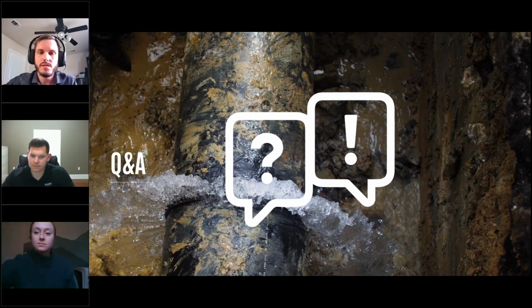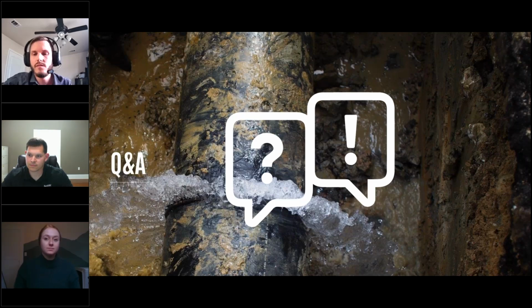But sometimes, like Calvin was saying, on a component, we always recommend putting it as close to the component as possible, to really get the best hydraulic effectiveness, so that there's not a large pressure drop between the component and the transducer. Okay, perfect. And so the last part of that question is, how many points of analysis are recommended for water hammer analysis?